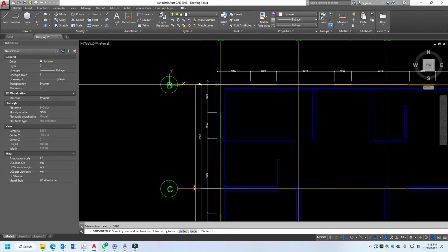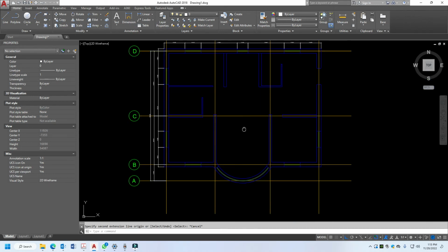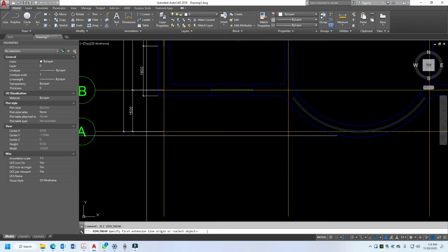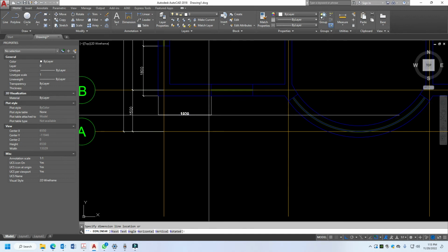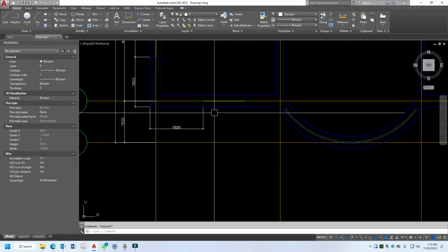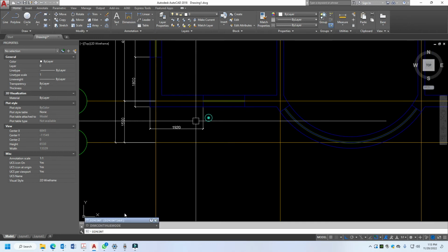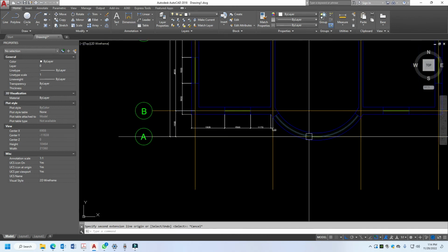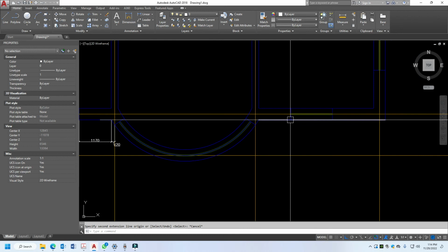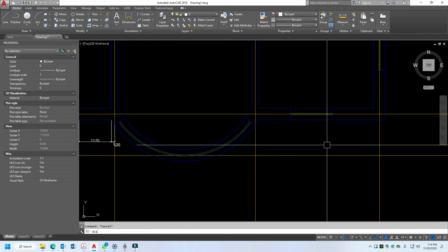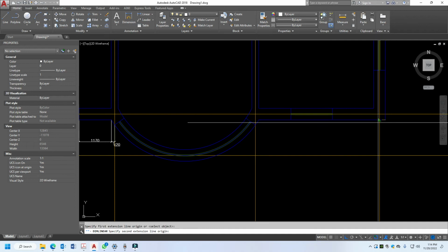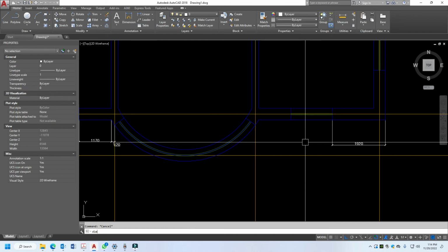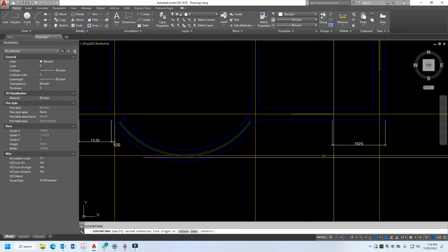And also here you need to have a dimension. Just type DLI, this one, drag, then DM continue, and then this one. And also here just escape, DLI space, then drag down, then DM continue again. Now it's balanced, the same dimension.